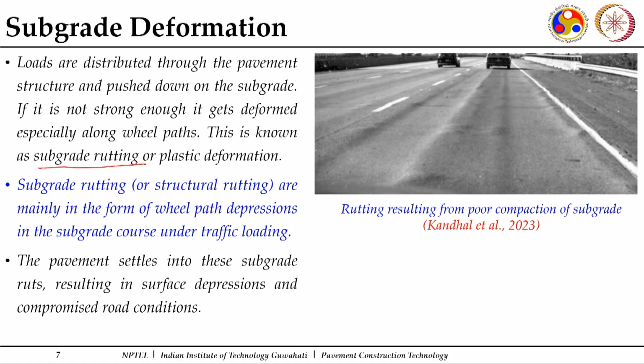So, you can see from this top surface, a bituminous surface, but here along the wheel paths you see some depressions, especially when vehicles pass, and these depressions are usually found along the wheel paths. Within the lanes, vehicles try to follow a particular path, and you will find the maximum amount of distress. Distress means anything in terms of some loss of material, some cracks, some depressions, or movement of some material.